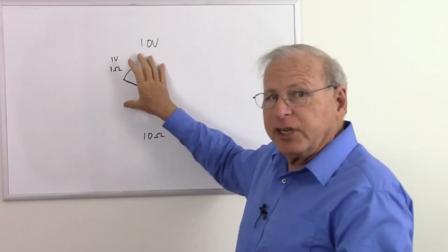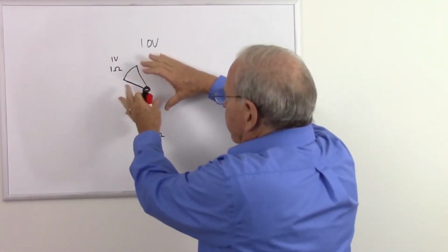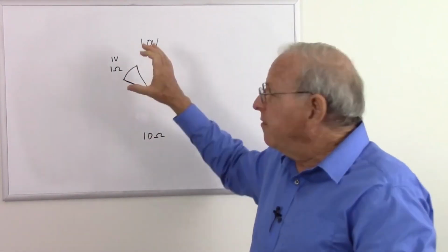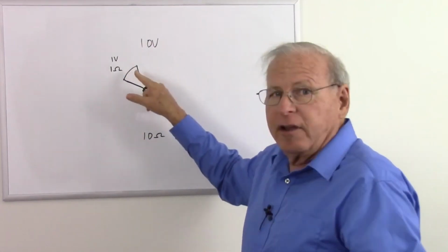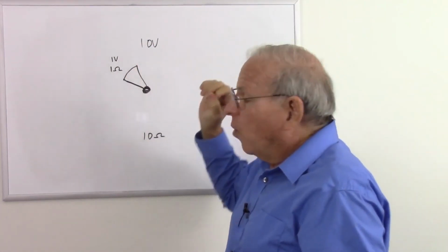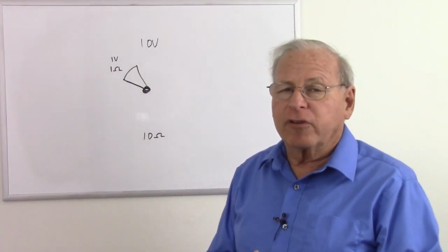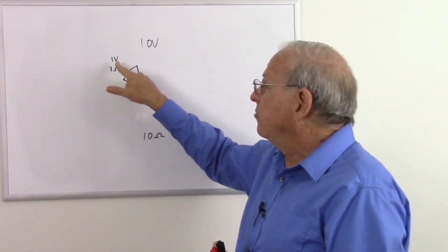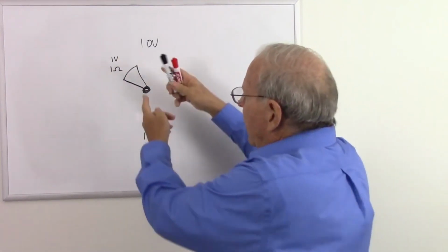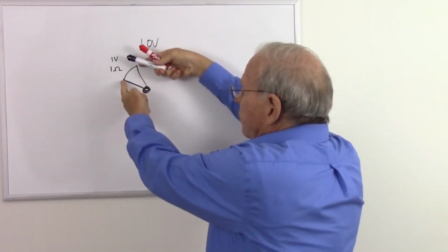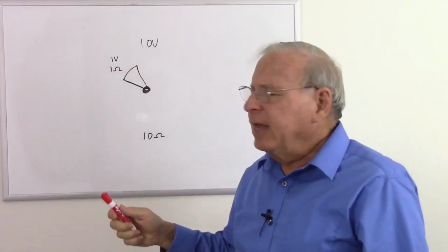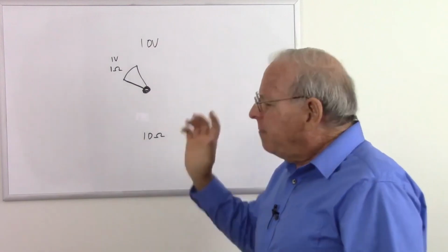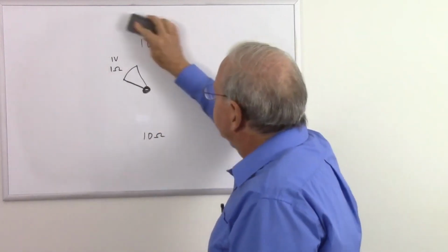We are imparting energy into the circuit. The magnetic field is coming from the center coil that's imparting energy into the circuit, so we have a power source here. It's the secondary of a transformer. So whenever you have a power source, any resistance in that power source must be analyzed in series with the voltage. Now we have the resistance along the whole section and we have the voltage across the whole section, but we have to analyze the voltage in series with the resistance. Let me explain why that makes sense.